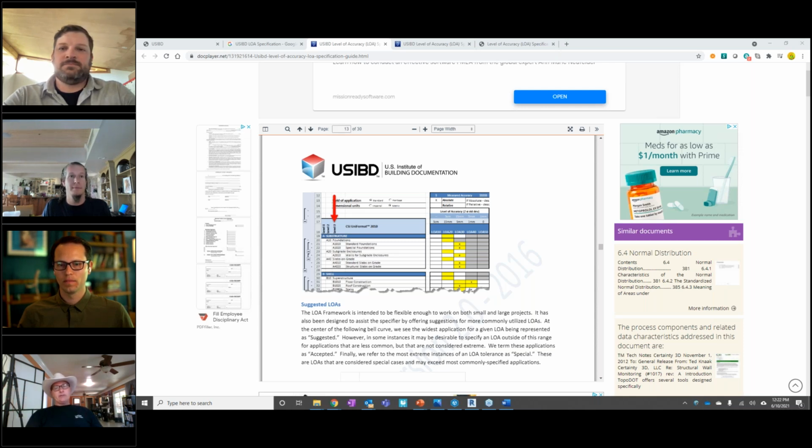And then when you talk about LOD 400, like Sylvia was talking about, that's getting into almost a spec sheet level of detailing where LOD 200 and 300 would not include nuts and bolts, whereas 400 would be getting down to that level, that level of construction value and where the exact holes are.